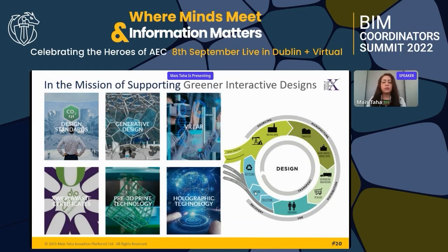And of course, always keep in mind what phase of the design you are designing for. Don't always assume that starting from scratch is the solution. Renovation is a good solution, a better solution if you don't have to demolish. And when you work in heritage architecture, you will always need to think of how to protect heritage first. So keep the life cycle in mind, because the life cycle defines the stakeholders, and the stakeholders are the decision makers, and the decision makers can help you to reach the optimum design and the optimum project results you want to reach.